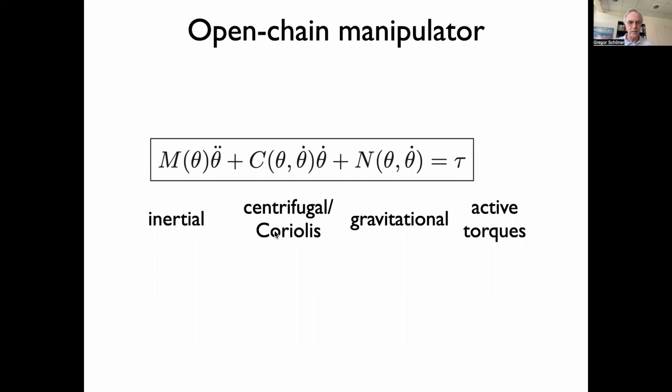Maybe I should make that idea somewhat intuitive. So what are these interaction torques? I'll make that intuitive. You see my face, right? You see my camera. So I can do something with my arms, and you will be seeing it. So for instance, when you have a 2-degree of freedom system, I take the elbow joint and the wrist joint. These are 2 degrees of freedom, let's say in a plane. And now I want to do a certain acceleration here and maybe a certain acceleration there. Let's say I want to have 0 acceleration at the wrist, so I want to move that rigidly, and have some acceleration here at the elbow.